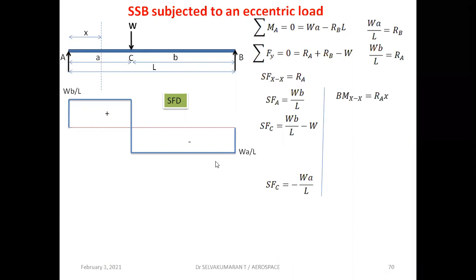And when you go for the bending moment, similarly write down the expression RA into x. At A, x is 0, so bending moment at A is 0. Mathematically you can prove it. So here it is 0.